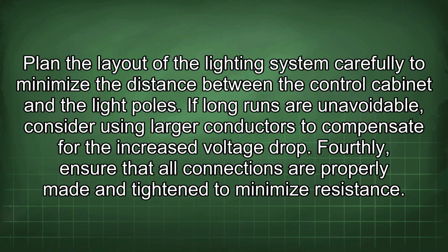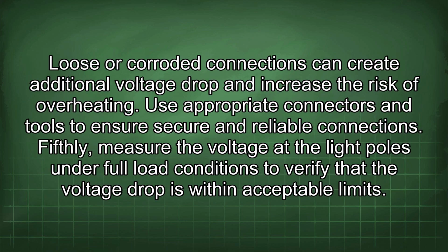Fourthly, ensure that all connections are properly made and tightened to minimize resistance. Loose or corroded connections can create additional voltage drop and increase the risk of overheating. Use appropriate connectors and tools to ensure secure and reliable connections.